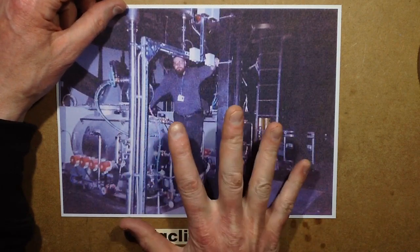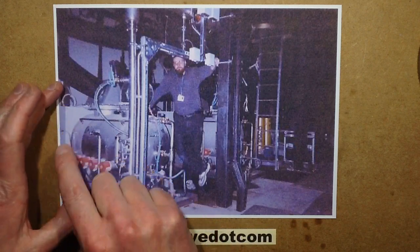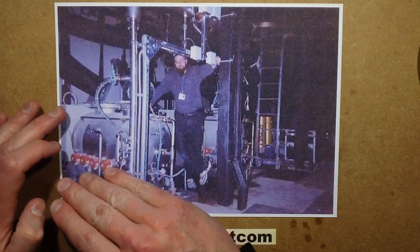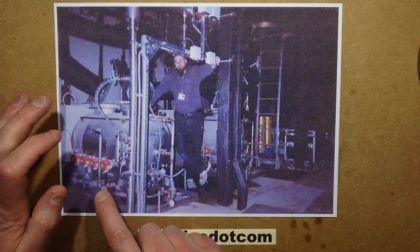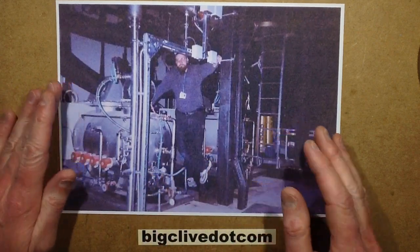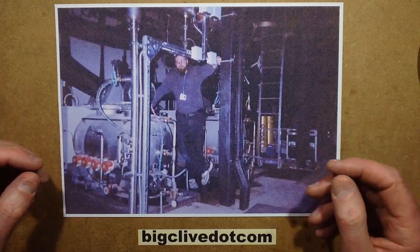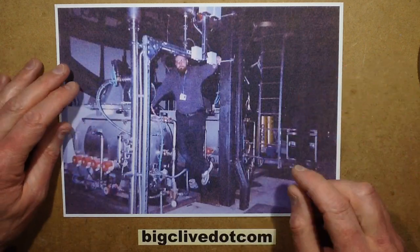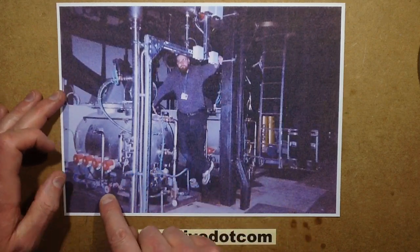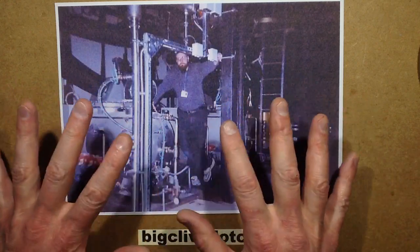These machines are huge, and the way they work is they have a control panel that meters water into these cylinders, and it's kept at a level where these heating elements, and there's just rows and rows of these elements on both sides, because it involves heating this water up to basically keeping it at boiling temperature and regular use, because this is a show that runs continually. So these heating elements heat the water up to boiling temperature, and then this pump down here pumps it up and sprays it into the chamber on demand.